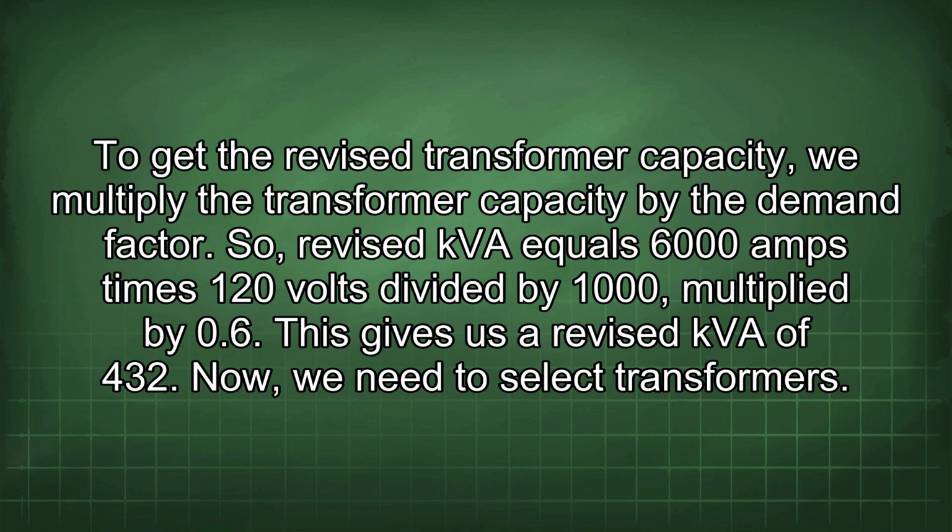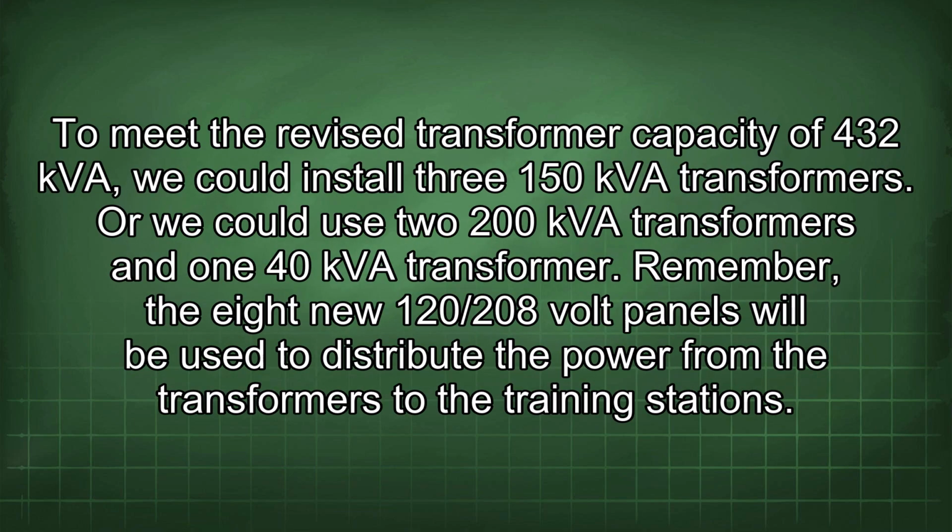Now, we need to select transformers. To meet the revised transformer capacity of 432 kVA, we could install three 150 kVA transformers. Or we could use two 200 kVA transformers and one 40 kVA transformer.